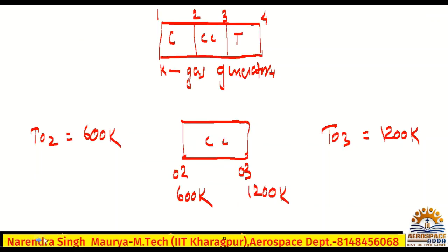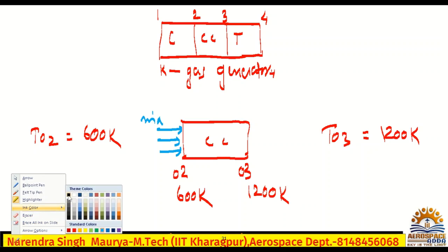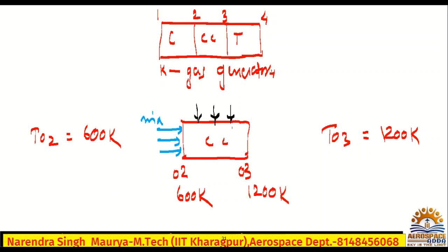So basically all the quantities they have given, they are talking about the fuel rate and heat value. It's simple. This is the airflow, and this airflow is nothing but m dot a. Then we are adding heat through fuel, so this is the fuel m dot f. And the exit will be the combustor products, m dot a plus m dot f.